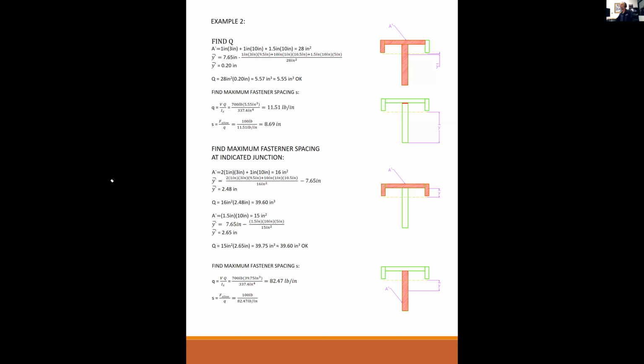So you had a bar wedged between 2 walls, and you put a load on it, or you changed the temperature, or you did both. You put a load and changed the temperature. And we had 2 techniques for solving for indeterminate uniaxially loaded members. We didn't cover that on the first midterm. That will definitely be wide open for this midterm.